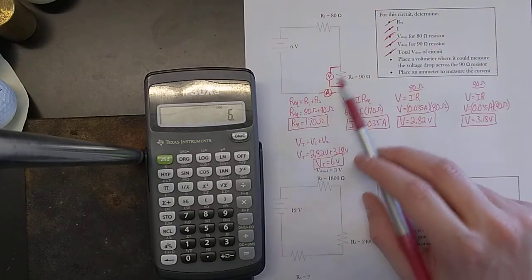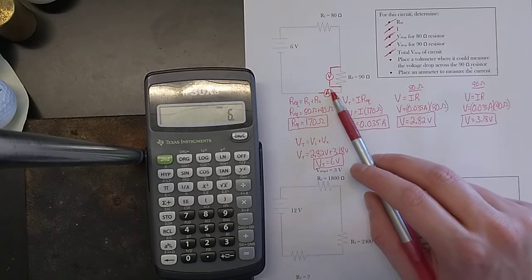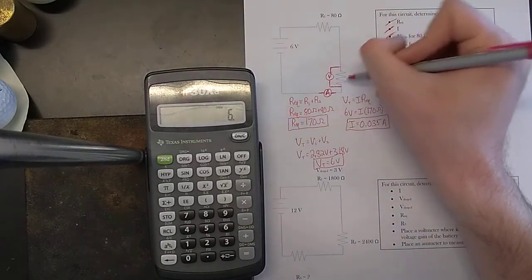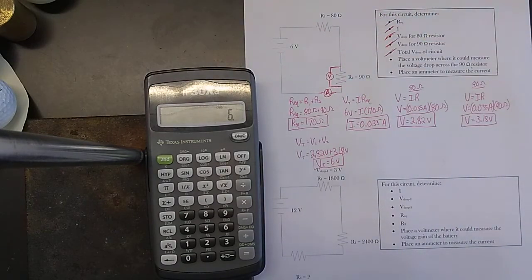If you were to do these reverse, if you were to put the V in like this, wired right into the circuit, or you put the A across the resistor, like this, that would be wrong. That would actually, in real life, possibly break either the voltmeter or the ammeter, especially the ammeter. You don't want to do that. There's a reason that you would end up doing that. I'm not going to get into it right now. I can talk about it in class a little bit, but that's a really easy way to fry the tools that we actually have in class, and these things are a little expensive, okay? They're not free. So we need to make sure we understand how to wire up a voltmeter and an ammeter.